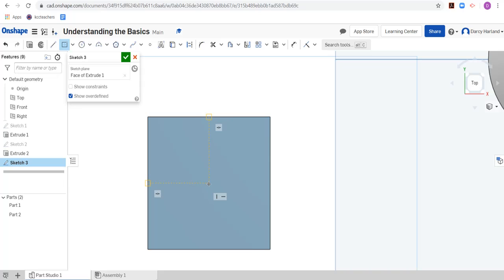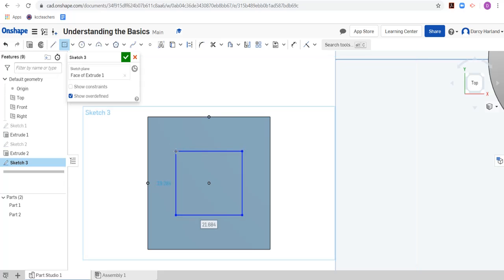So I can click down now from that center point, and you'll notice it gives those little circles here and here from those marking points. So it's essentially using those points as a point of reference for this rectangle. Okay, so I'm going to make my rectangle now. I don't really know how big I want it just yet, so I'm just going to click randomly here, but the size that I'm going to make it is a 20, enter, by 20, enter, rectangle. Okay, so I've made a square, 20 by 20.